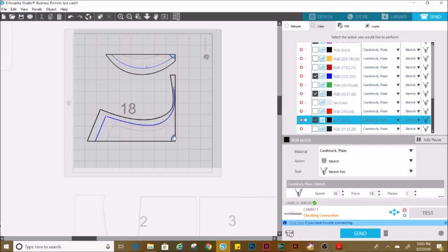And again, go in here and change these into sketch lines, so that way it can draw your line right there. So when you connect your patterns together, you'll have that little piece there. And the same thing with this one. You don't need this top piece. You just need that and this, and you would sketch line that as well.